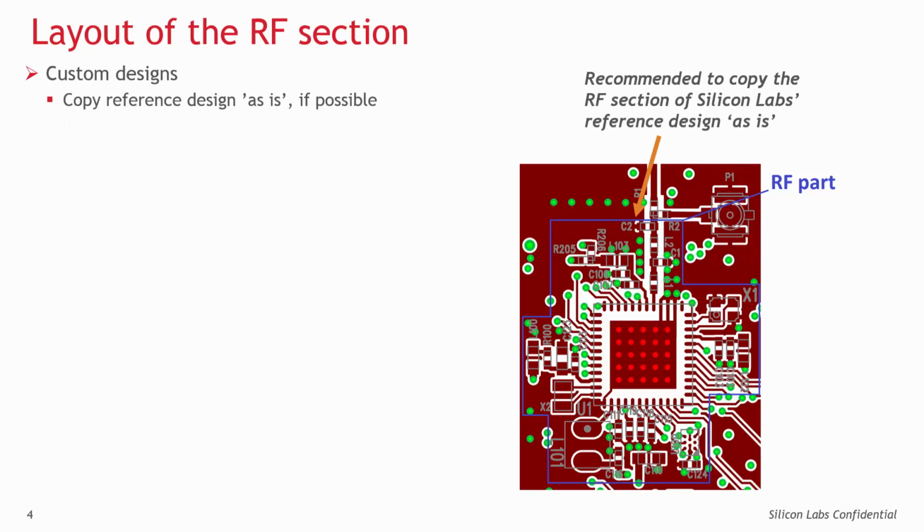The reference schematics and layout designs of the matching networks are usually provided by the manufacturer of the RFIC. It is recommended to copy the entire RF area from a reference design as is. Of course, it is not always possible due to size restrictions, different form factors, etc. Thus, a custom design may need to deviate from the reference one. Although the size of a matching network is relatively small, due to the high frequency, the matching is sensitive to the physical parameters of the matching layout, besides component values, of course.